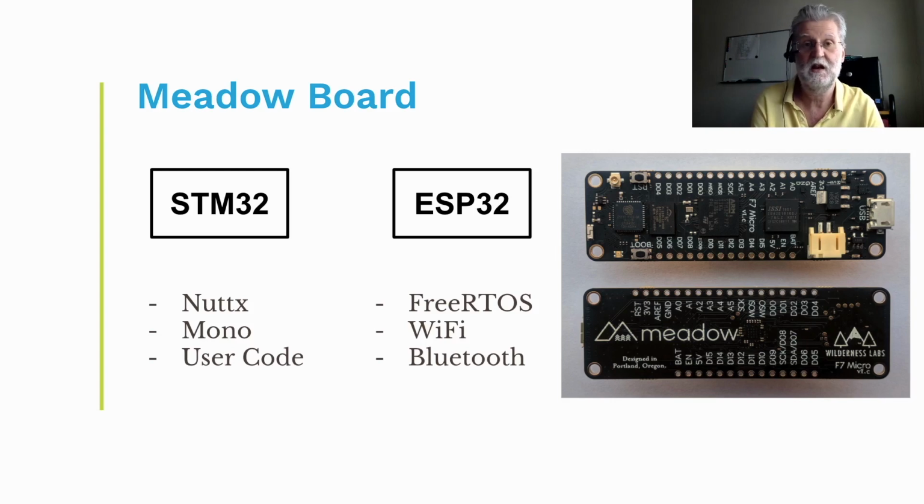This architecture has a couple of advantages which you won't find in any other microcontroller. The first is that the ESP32 can be turned off. So if you're gathering sensor data out in the field and you're running on battery, then you can turn the ESP32 off when you don't need it, and this enables you to extend the runtime lifespan of your battery.